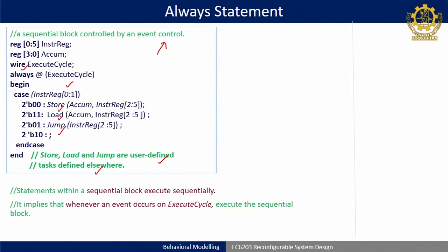Okay. So, if there is more than one statement, you have to write begin and end. Sometimes I saw that in simulation tools they take case as a single statement. So, we start from here, end at here. Begin end sometimes is not required, but anyway it is to demonstrate that if by chance you find more than one statement, you have to use one begin and end. And here again the body of the always block is a sequential block, the body will execute sequentially.